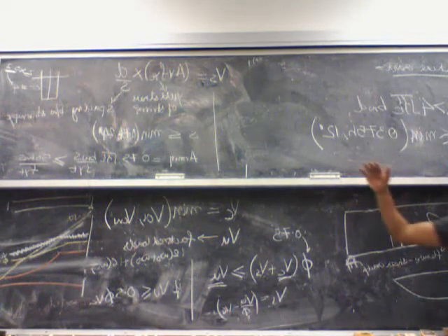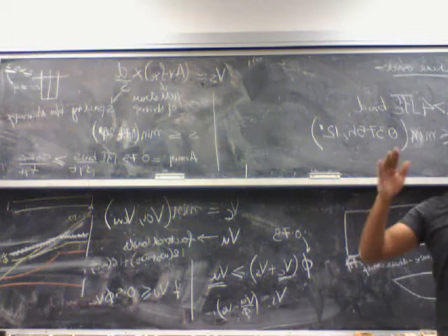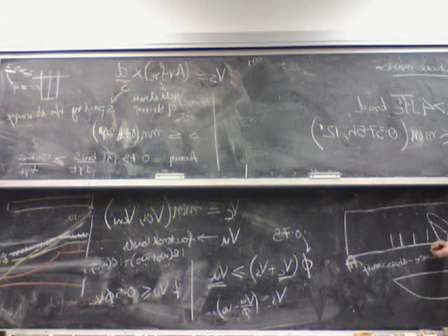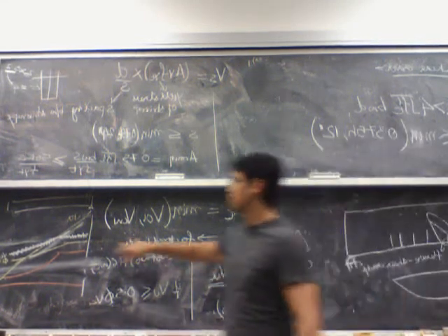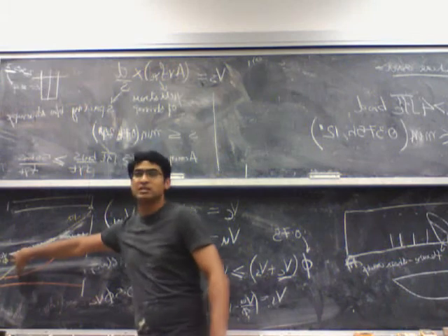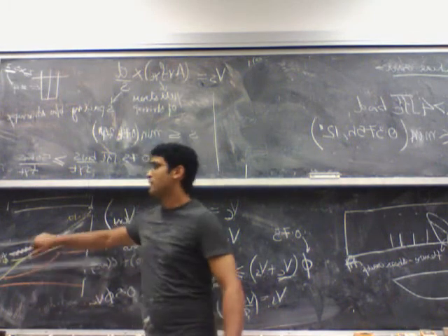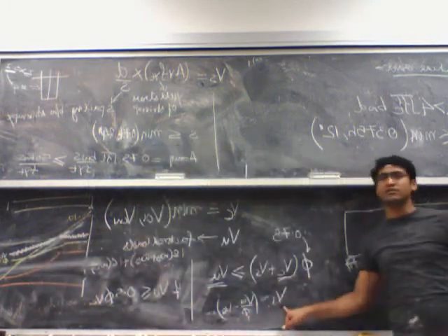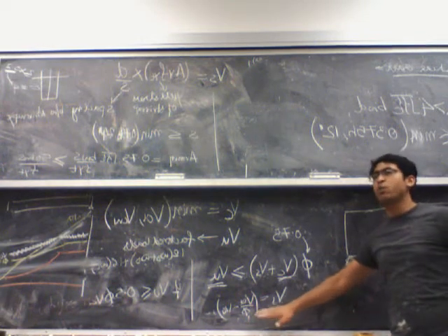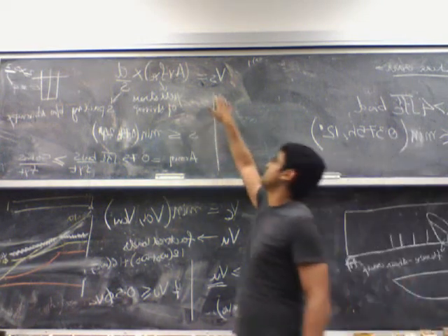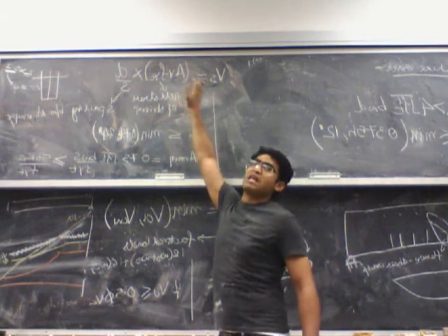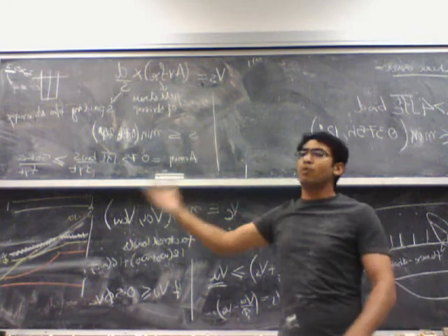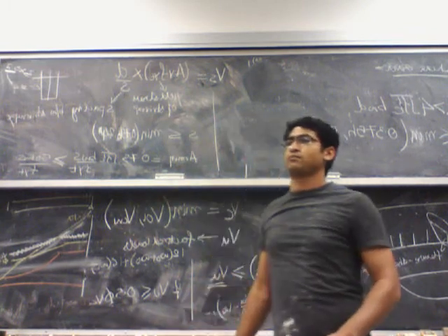The whole idea is first find out VCI, which is the flexure shear capacity. You find out VCW, which is the web shear capacity, and the actual shear capacity of the concrete is the minimum of the two. This actually becomes your VC. Once you have the VC, you can calculate your VS. And depending on what the value of VS is, you can calculate your spacing and the value of AV, where AV could either be the minimum value or more than the minimum if required.